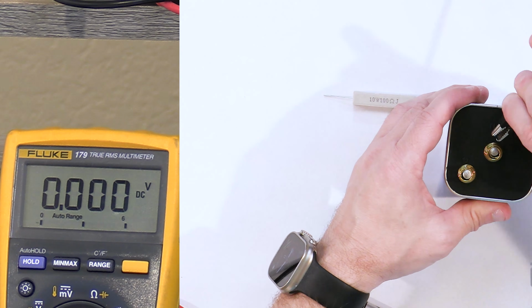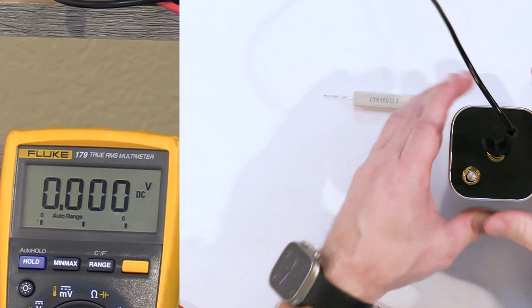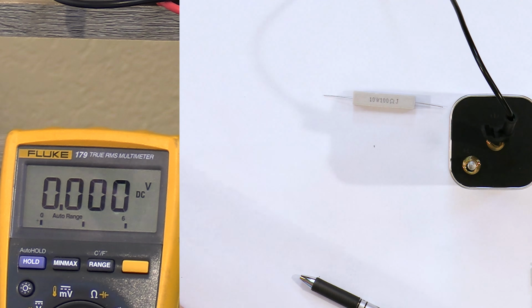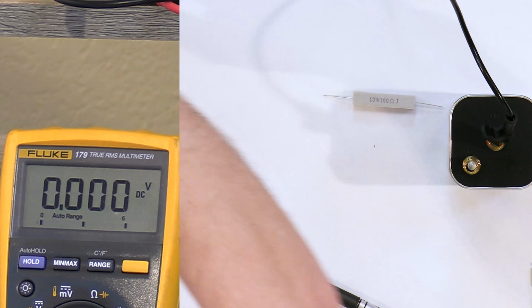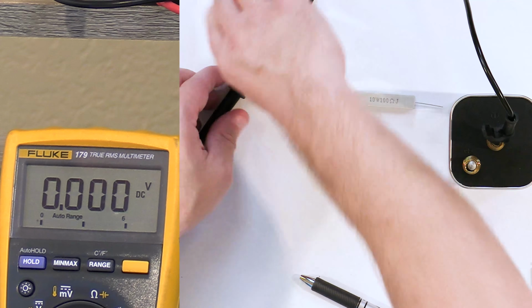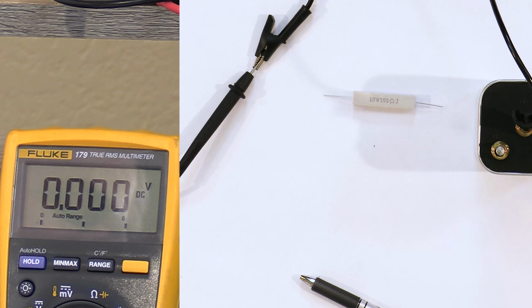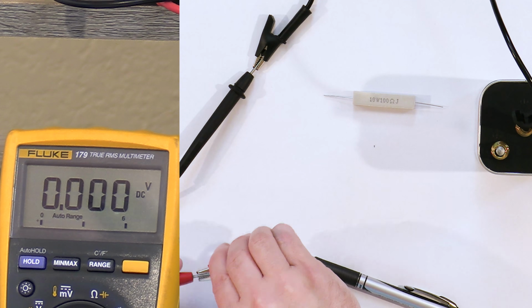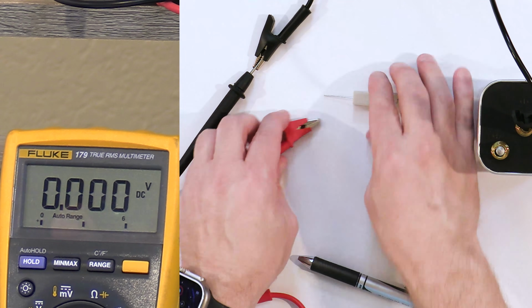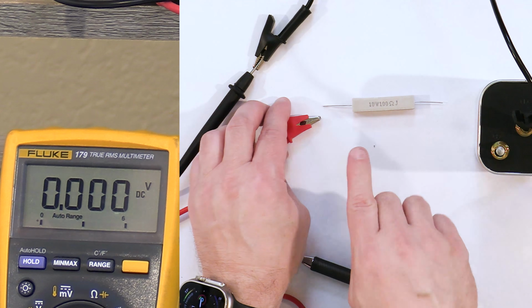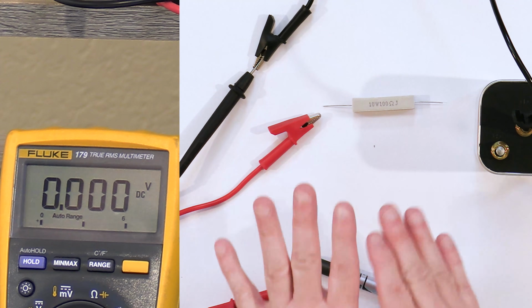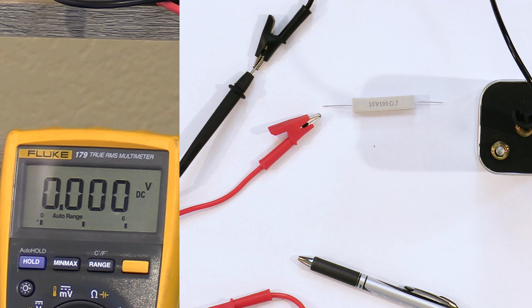So I'll clip this battery, connect it right here, and then it will come over and I'm connecting it right here to my ammeter, measuring the electric current. Then it's going to go through the meter, and then the meter is going to come over here where I'm going to connect it back through the resistor again. So all I've done, I'm still connecting it directly through here, but the current is also flowing through my meter so that I can measure.